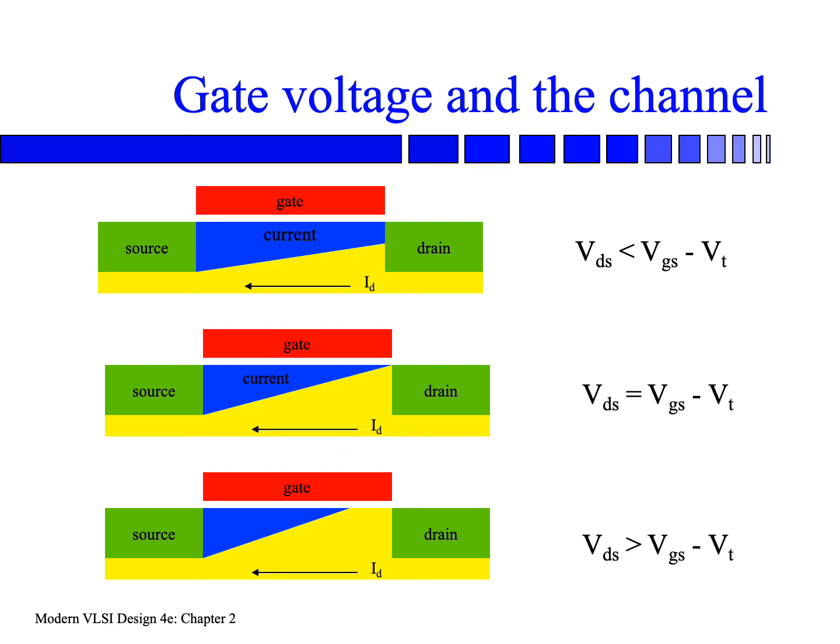Then if they are equal, at this kind of boundary, VDS just equals VGS minus VT. As a result, the gate and the drain essentially differ by just the threshold voltage. So the channel just forms between them, close to the source part, and the channel is formed over there. They can conduct current very easily. Overall, there is still a current flow from the drain to the source.